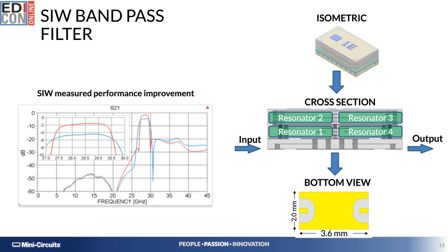We are developing as we speak, and we have actually implemented also in some of our developments, technological advances related to via implementations for these substrate integrated waveguides. We're employing also higher conductivity silver pastes and lower loss dielectric materials.